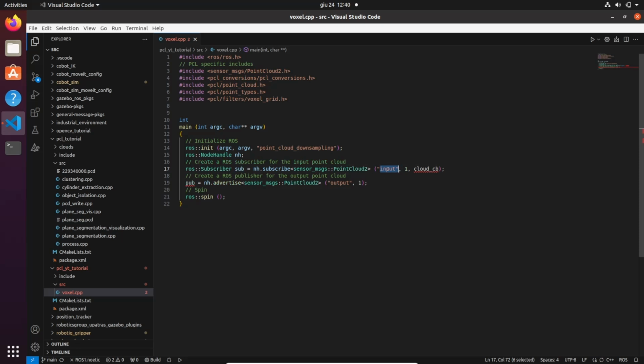This topic input is of type sensor_msgs PointCloud2, and in this way we are going to tell from the terminal what topic this subscriber will subscribe to. We're going to see that in a while.